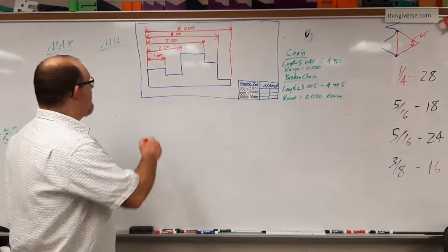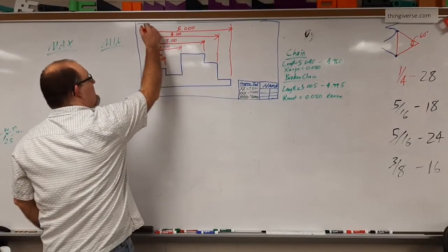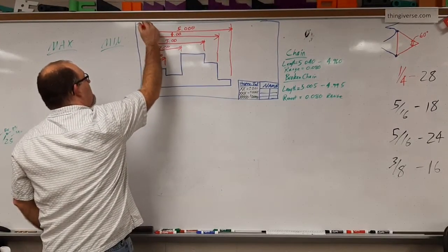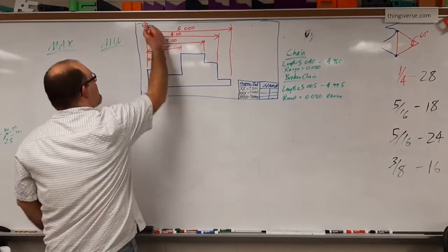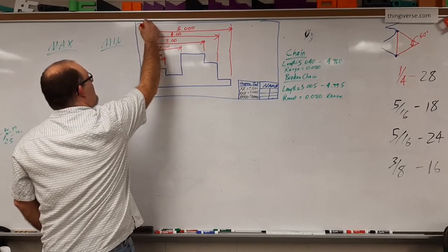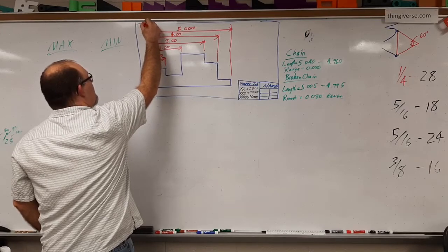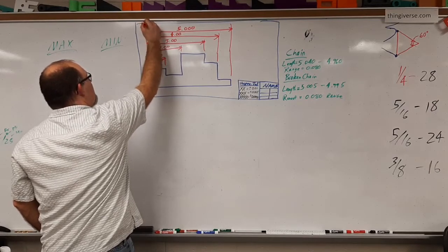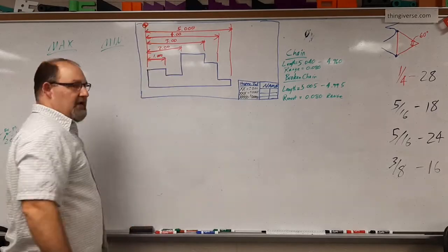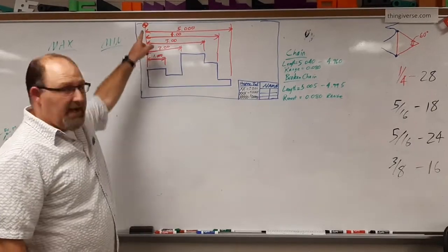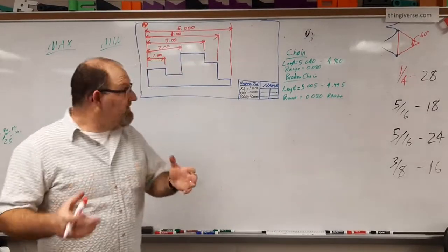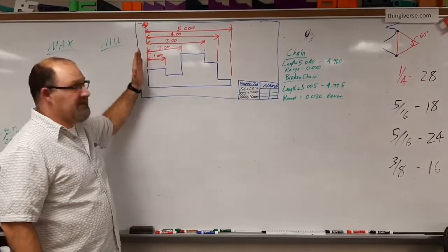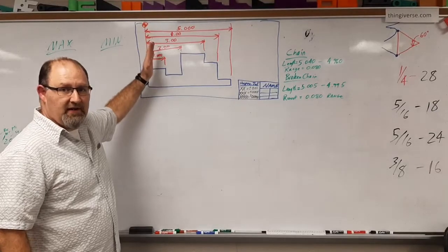So a lot of times you'll see a datum edge or a datum point, sometimes it'll have a symbol. That symbol may be a circle with a cross in the middle. A lot of times there will be colored out spots like this. You can see that there. So this type of symbol would be a reference to a datum type symbol. With datum dimensioning, that is dictated simply by all these arrows being on the very edge here.